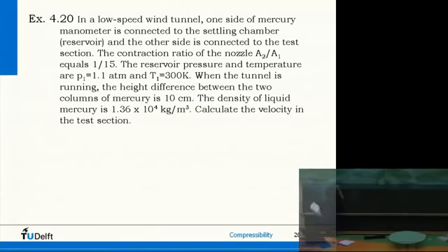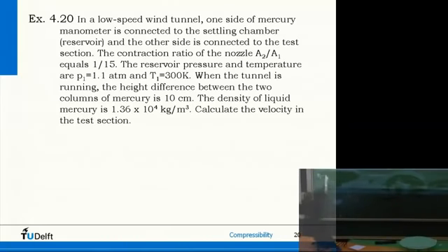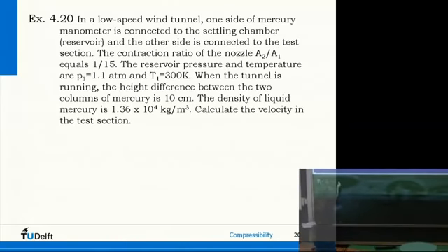So here was rho g h. Could I have said P2 minus P1? No. Because you have to realize which one is the low pressure. For incompressible flow, it is the one with the largest area, right?